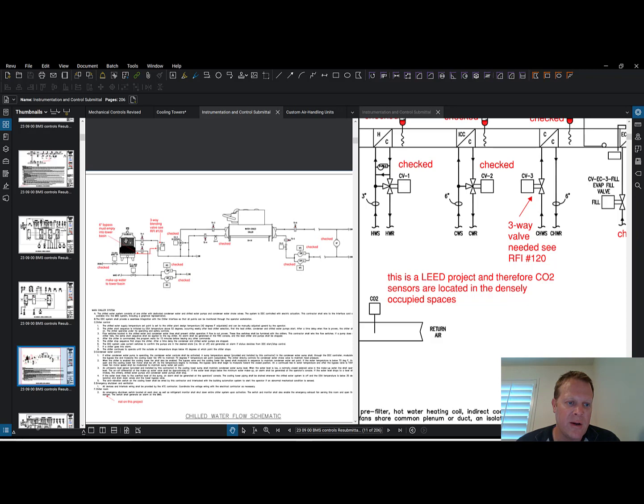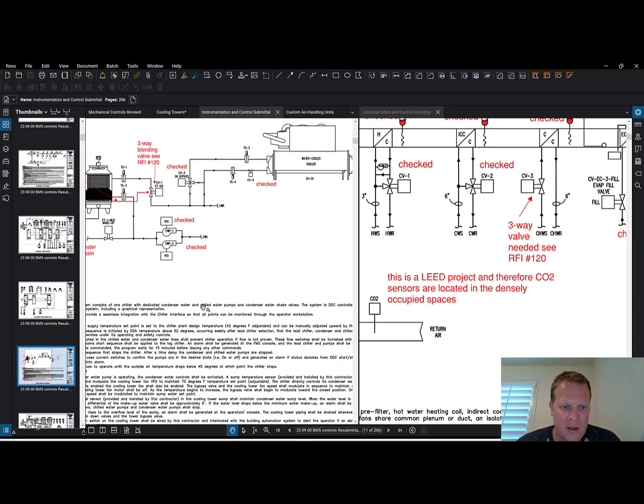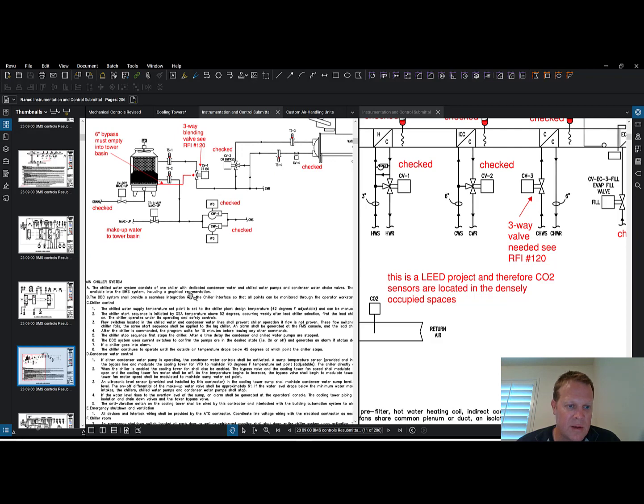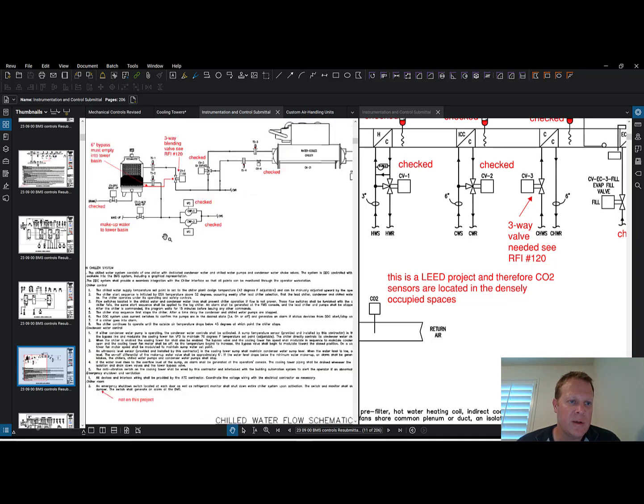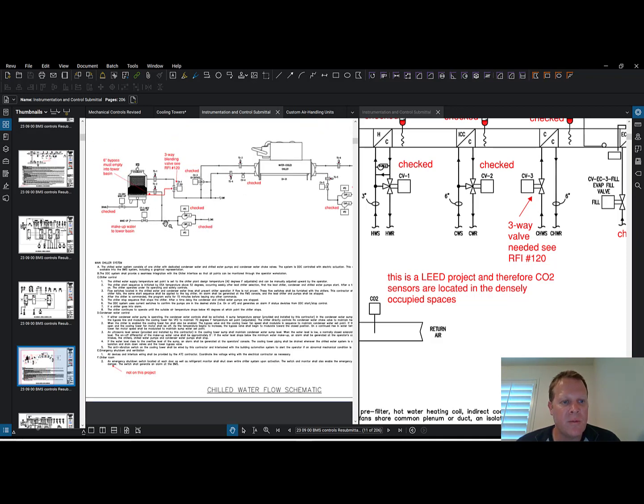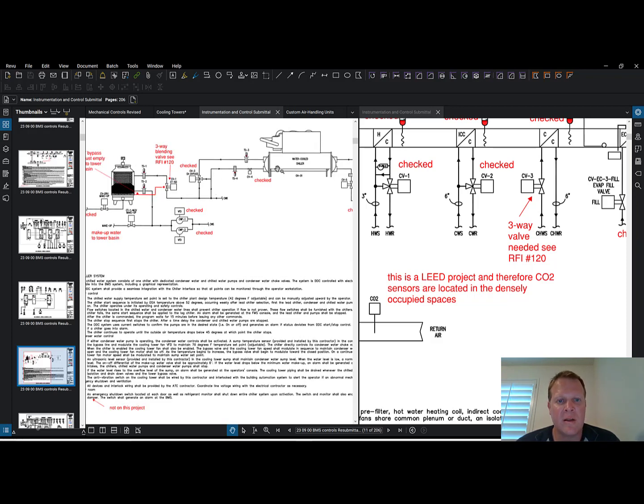I mean, this cooling tower over here that they're actually calling... what are they calling it? They're calling it condensing water, but that's a cooling tower. What this is doing is getting water, and the water is getting pumped over the top and constantly feeding in here. The water that gets cooled off because air is blowing across it ends up coming into the chiller and taking some of the heat out of the chiller so that it can then get back. I don't know.